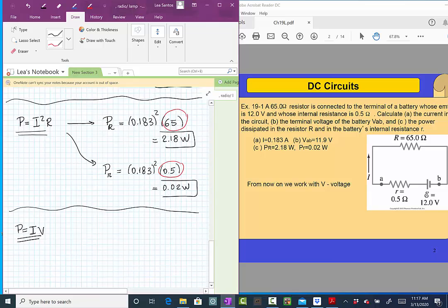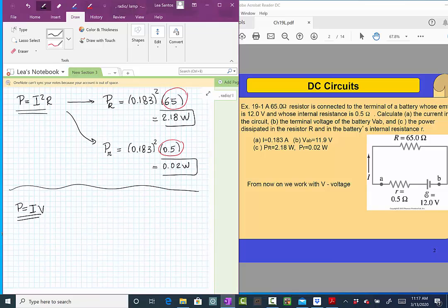So let's go again and write that circuit that we have. So here we have the EMF. We said that this is the potential V1, which as it goes through the resistance, it drops, becomes the potential VA. And then after that, it's the same everywhere. This is VA, this is VA, up to the point where we go through the big resistance, our device. Then we have another drop, it becomes VB.